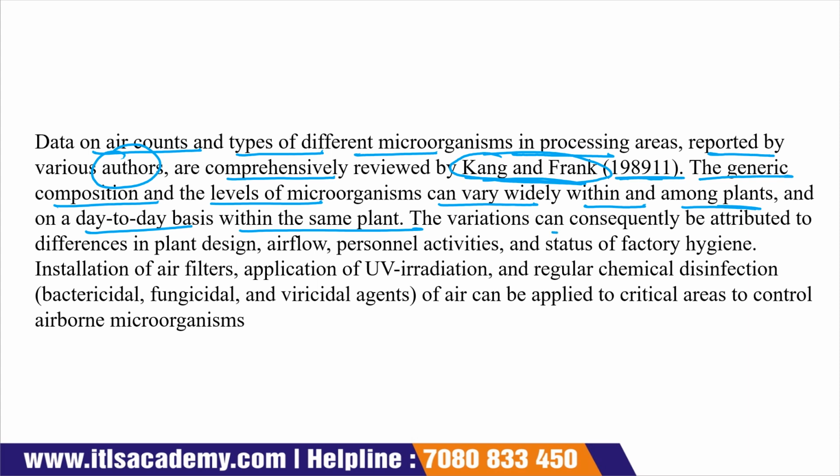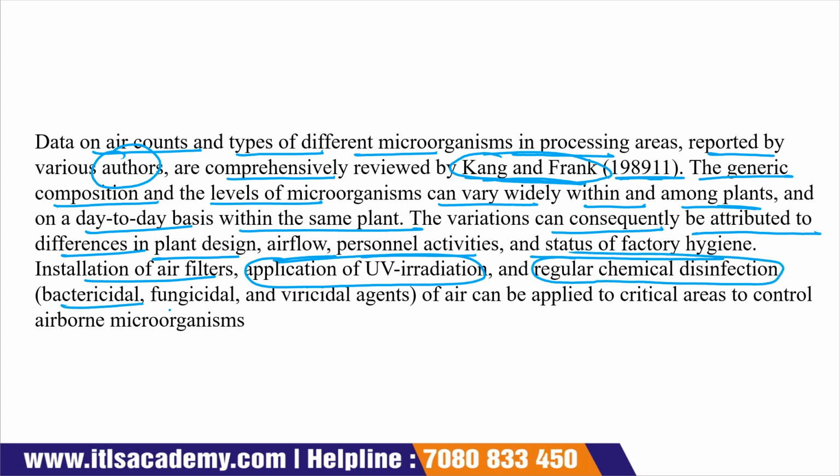The variation can consequently be attributed to the differences in plant design, airflow, personnel activities, and status of factory hygiene. Installation of air filters, application of UV radiation, and regular chemical disinfection like use of bactericidal, fungicidal, and virucidal agents can be applied to a critical area so that it will control the airborne microorganisms.